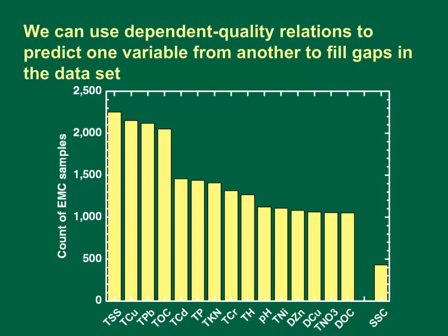We can use total suspended solids concentrations, which have the most values in the highway runoff database, to model suspended sediment concentrations, which have fewer samples and sampling sites. Furthermore, this method allows us to produce regulatory total suspended solids concentrations from the highway and BMP and lets us model more realistic sediment concentrations in the upstream and downstream flows.